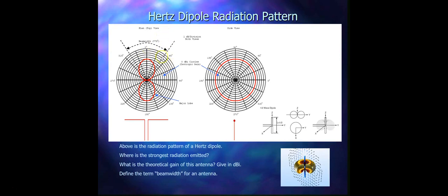The beam width looks directional. It is actually focusing in one direction, but it is not very effective. If you are targeting a radio signal at a remote location, then this is not going to be very effective. So in conclusion, we can say that the narrower the beam width, the larger the gain of the antenna will be.